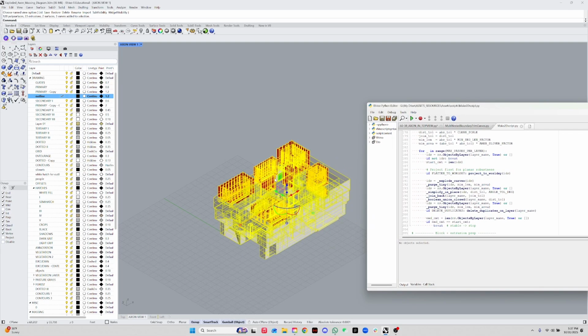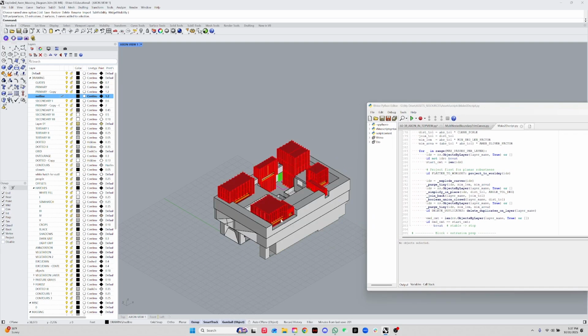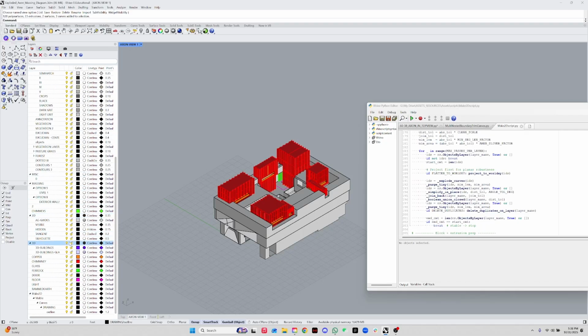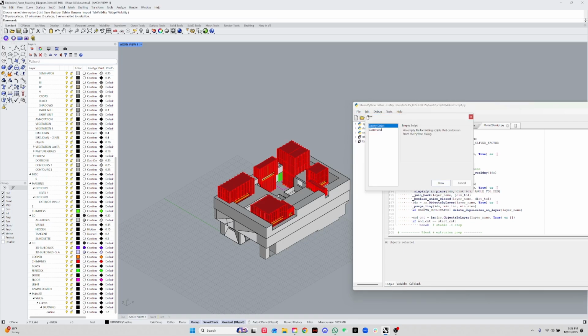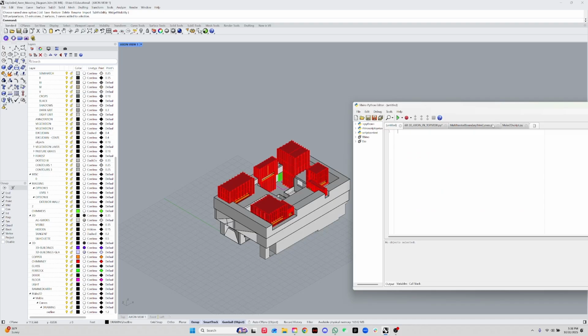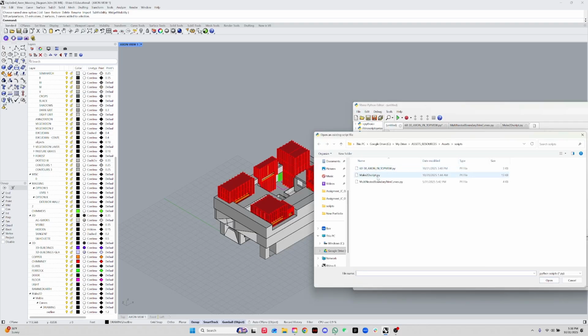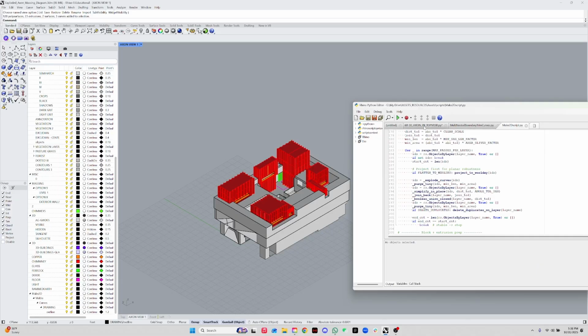So we're going to use the script that I have given you guys, the Make2D script. What that script is going to do is give you a more thorough Make2D line work, and it's going to look way cleaner than the regular Make2D. So to use it, make sure you go File, then New, Empty Script, and then you just open that script. I have it right here, which is the Make2D, this one. I already had it inside. So it's going to show up.